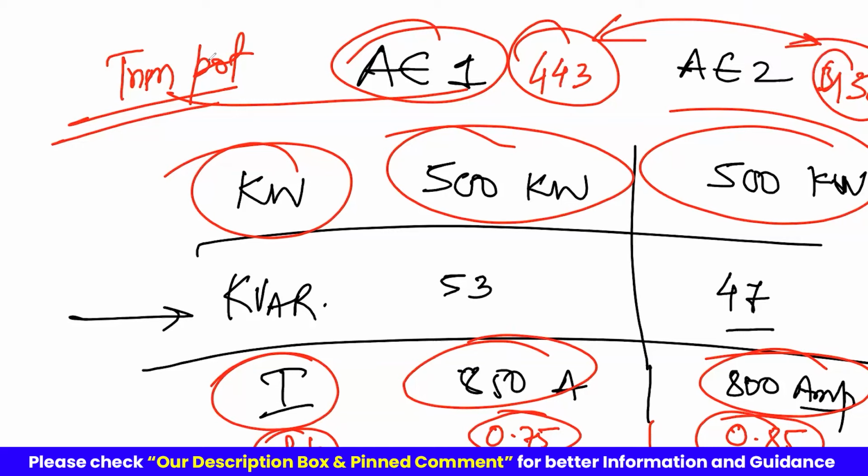Sir, one doubt. Actually, by using this trim pot, we are adjusting the exciter field current, right? Yes. There is one more setting inside, the droop setting, which nobody touches. It is factory set, so imagine that it was correct. If nobody tampered with the droop setting, there should be no problem. The trim pot is basically a set value. You're changing the set point of the voltage.